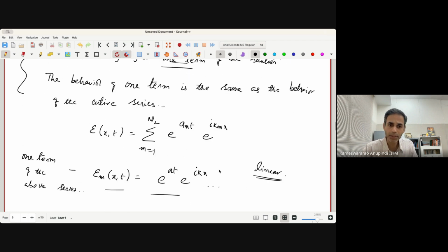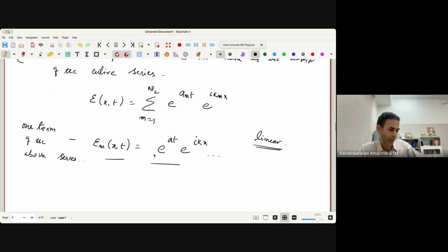So what we have done is we obtained a governing equation for error, which is the same as the governing equation for the quantity that we are solving for, that is temperature. Then we said this governing equation is as difficult as the original problem itself, so we will come up with a model for round-off error. Round-off error looks like a random fluctuation, a random function. Any random function can be written in terms of sines and cosines using a Fourier series. Out of the several terms in the Fourier series, we discarded all the remaining terms other than m equals 1 to N by 2, because they are not going to fit into the domain that we have discretized.